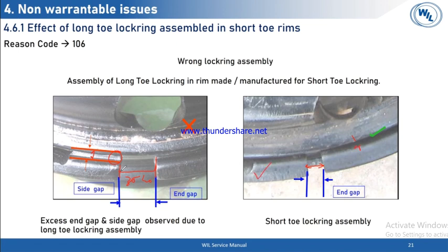The reason is, after we put the tire inflation inside this assembly, it will never come out. But there are some chances that the lock ring will come out during tire assembly if we use the wrong one.